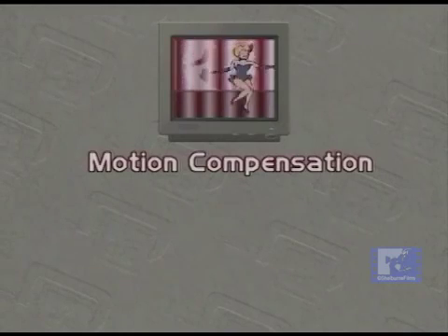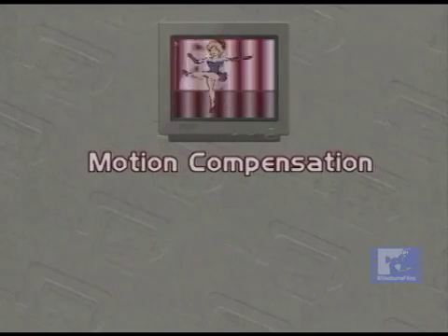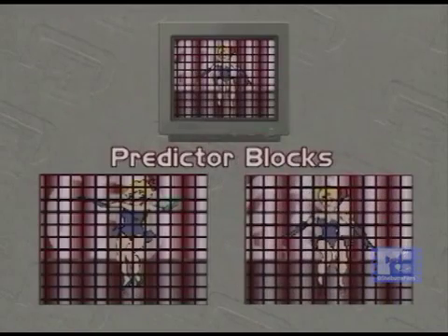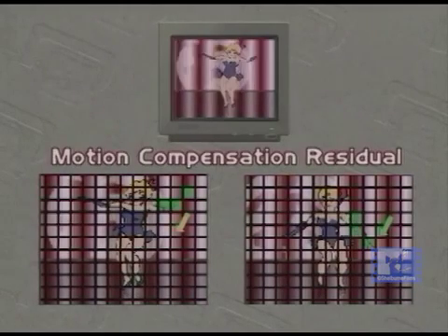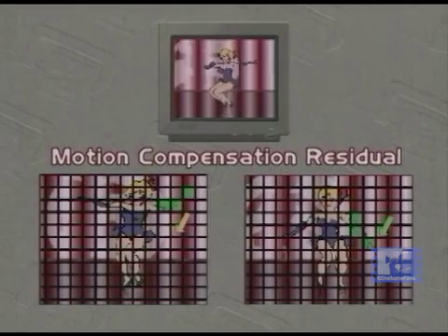Motion compensation is used to compute the direction and speed of moving objects within the video image. All macro blocks are scanned to identify those portions which will not change position. Predictor blocks also are identified, with their position and direction of motion noted. Only the relatively small difference, called the motion compensation residual, between each predictor block and the affected current block is sent to the receiver. If all of these differences are communicated directly to the receiver, then no distortions or artifacts will be visible in the displayed image. Artifacts will be introduced whenever there is an insufficient number of bits available to communicate essential image information and rapid motion changes from one frame to the next. In this case, it is a trade-off between bit rate and image fidelity.